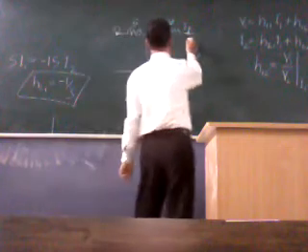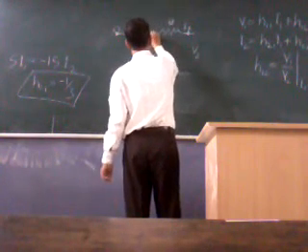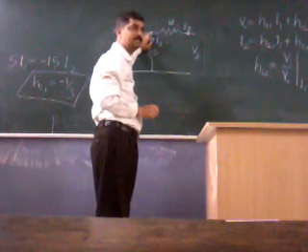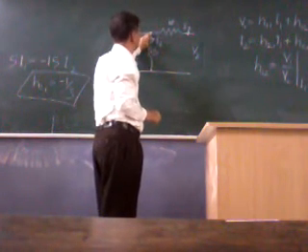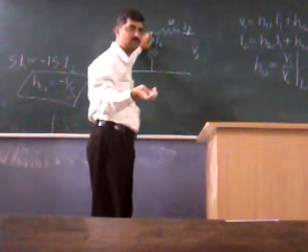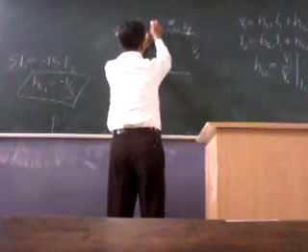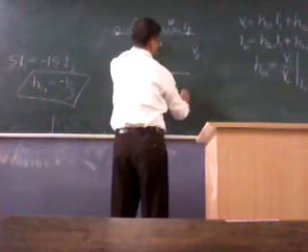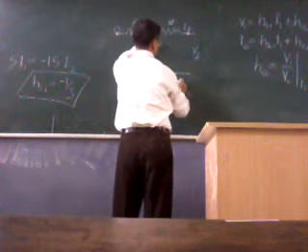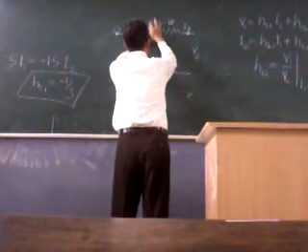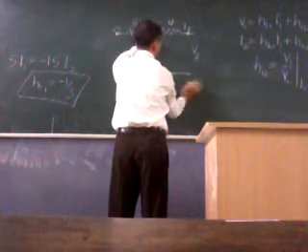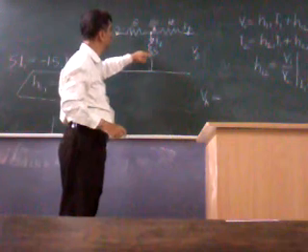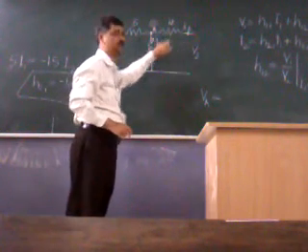So if we apply V2 here, what will be this voltage? If I call this point A, VA would be, since this current is not flowing, 5 upon 5 plus 10 into V2.